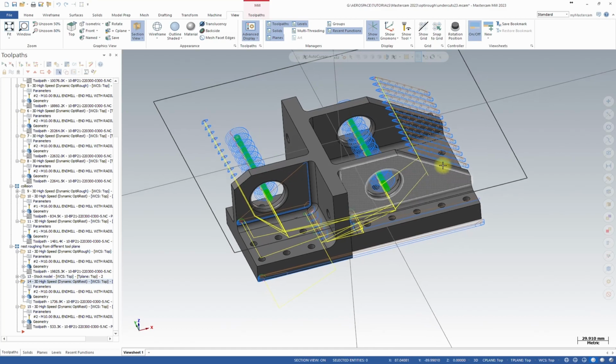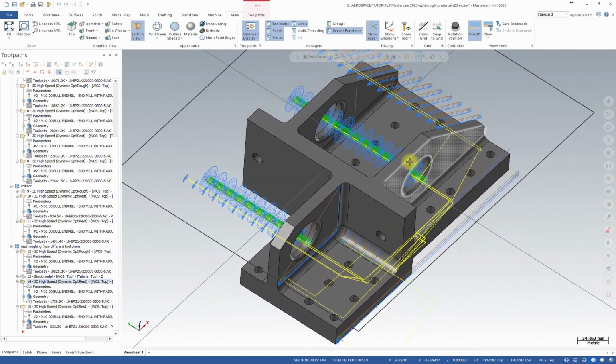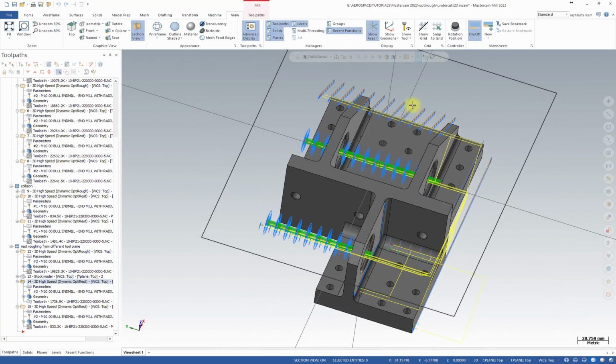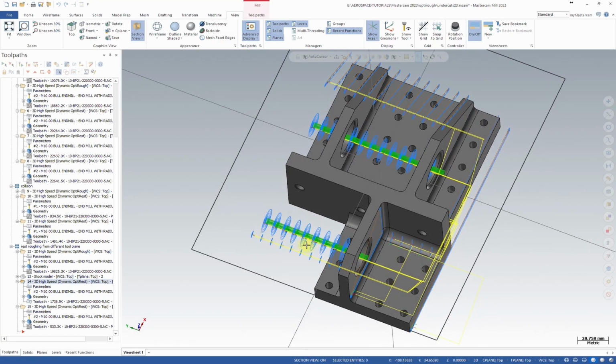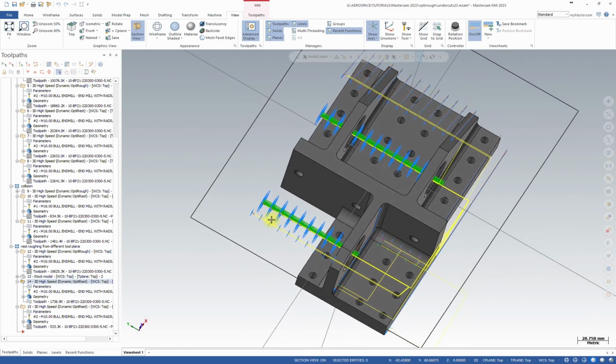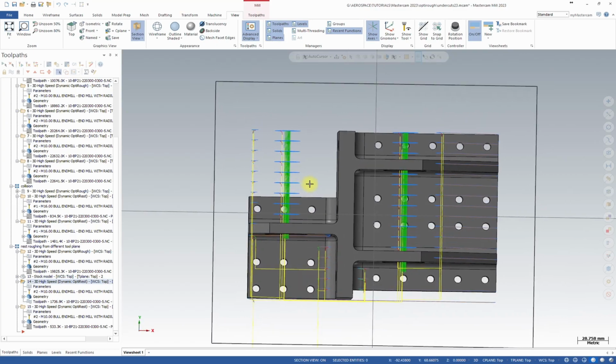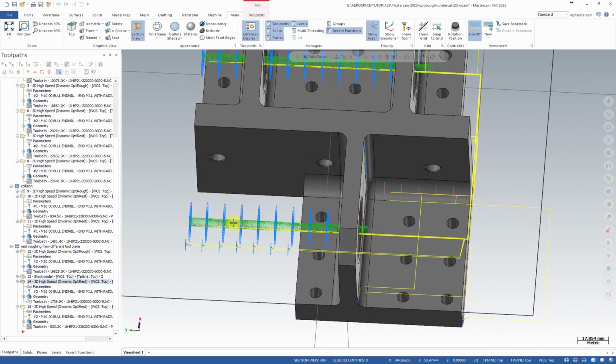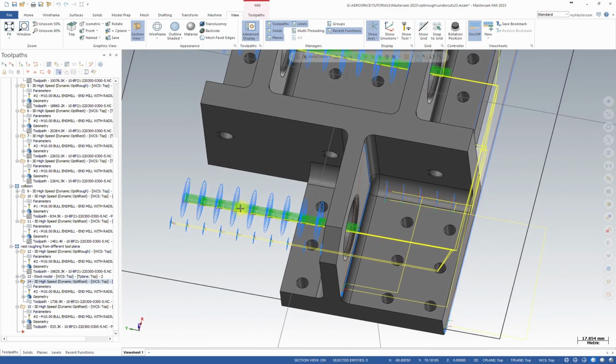And yes, this is the result from Mastercam 2022. So as you see, we do rough the whole rest of the material, but Mastercam extends those toolpaths all the way to the end to the bottom of the 3D model. And this is a lot of air cuts produced in this operation.